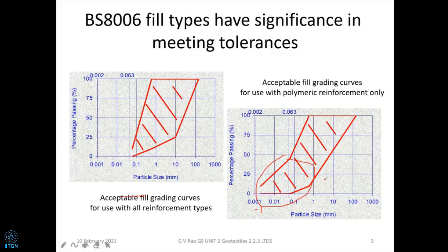So these walls are cheap, sorry, cheap is not correct, but inexpensive. Particularly in the areas where good sand is available, that means coarse sand, good frictional property is going to be there. Why? The higher the compaction on a sandy soil, obviously we are going to have more and more phi. If the phi is going to be 40 degrees, let us say, naturally the earth pressure is going to be less. You know that the more the friction angle, the lesser the earth pressure. So the length of reinforcement required is going to be less and less. And also it helps us to construct, because we don't have any pore pressures during this.